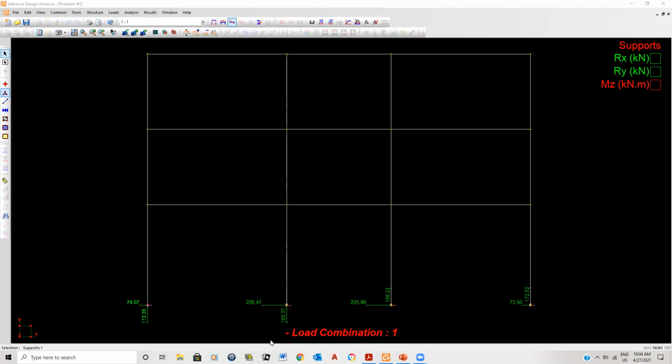And what I find interesting is, first of all, in the X direction they're all going against the direction that the forces are being applied. But what I like about the Y's is that 2 of them go down, 2 of them go up. So it kind of shows you where the building is being overturned. If these reactions are going down, that means this part of the building wants to go up and turn over like this. That's what they mean by the overturning of the building. So that's why this is going down, that's going down. And of course, it's overturning somewhere around here, and therefore this is pushing up and that's pushing up.